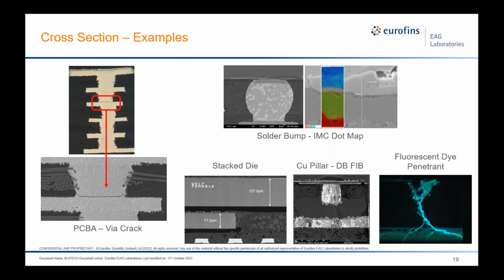On this particular analysis, we likely performed some non-destructive initial investigation steps, like scanning acoustic microscopy to make sure there isn't large gross internal delamination within the board, and then maybe an X-ray to see that there are no missing vias or anything significant of a construction nature. And maybe through TDR, we know that there's an open within this via stack. So by cross-sectioning and maybe doing an ion mill to clean up some of the smearing artifacts, we were able to locate the fine crack.